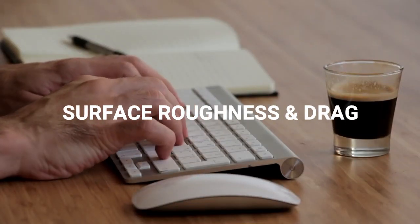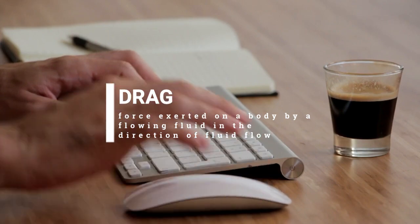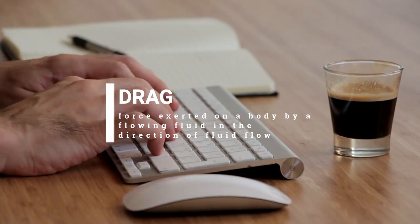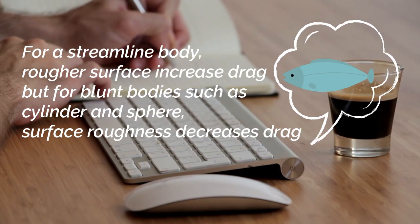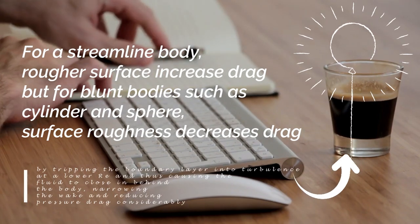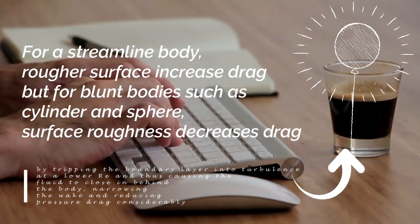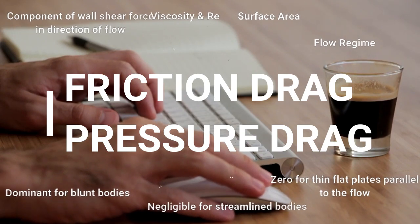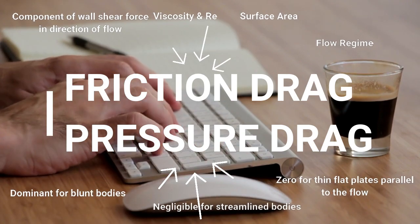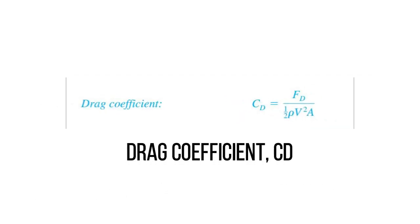Looking into the effect of roughness. Drag is a force exerted on a body by a flowing fluid in the direction of fluid flow. For a streamlined body, a rougher surface increases drag, but for blunt bodies such as cylinder and sphere, surface roughness decreases drag. There are two types of drag, which are friction drag and also pressure drag. And these drag characteristics are defined by the drag coefficient equation.